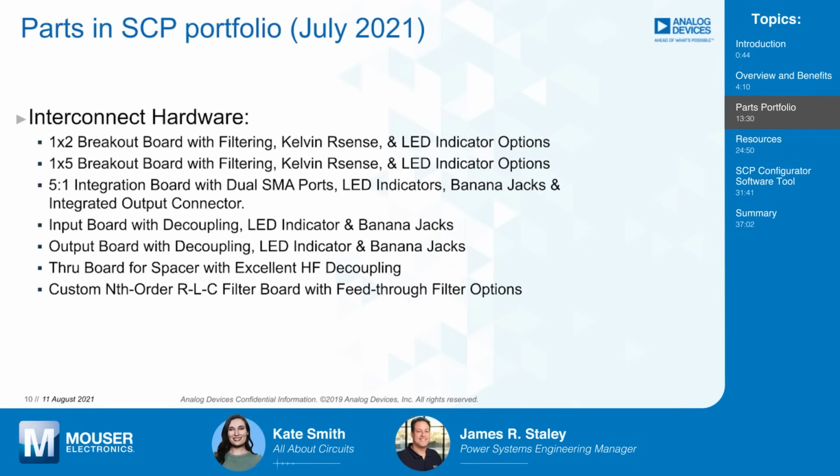Interesting. So that's where that simulation sort of piece of the puzzle comes in. Actually, it's not simulation. It's real hardware. That's the great thing. Sometimes people want to do their entire designs in SPICE, and that's a great tool. The problem is it's really hard to simulate parasitics. This board actually gives you, depending on how large your array is, some real parasitics you can measure.